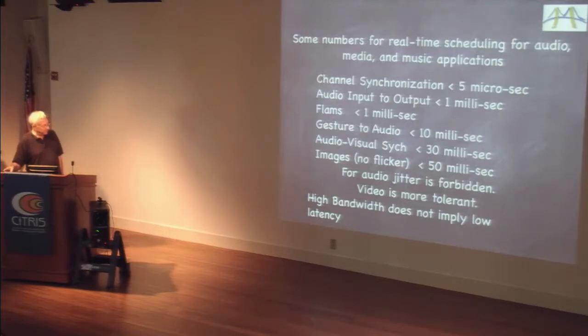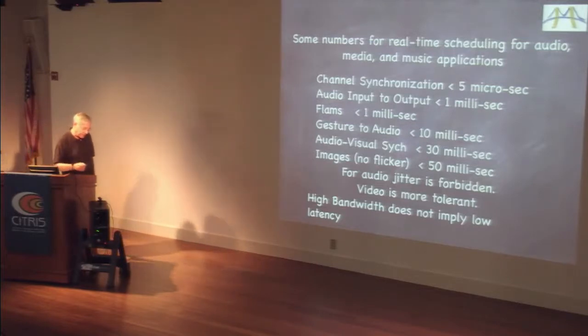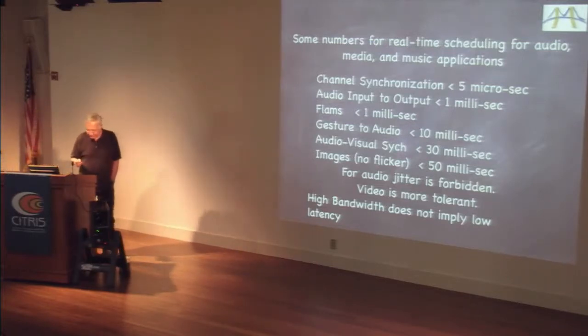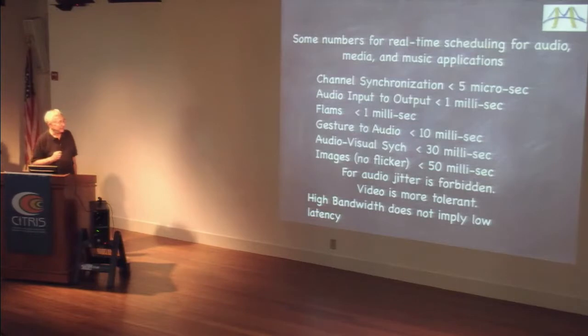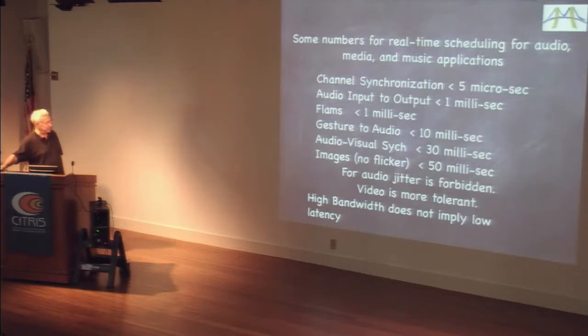Now, here's another important concept. Just because something computes quickly or has high bandwidth does not mean we're going to have low latency. In fact, one of the problems with GPUs for most of the musical applications that we've attempted, where we really try to keep the latency down, we've had trouble getting things in and out of the GPU in a satisfactory manner to keep the latency low, even though the computational bandwidth is fairly high.